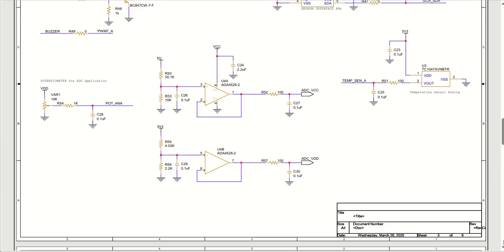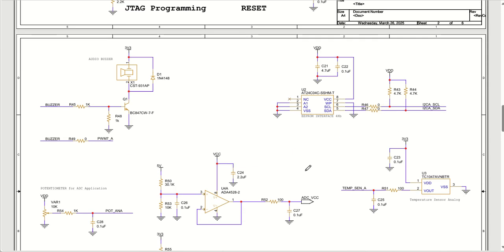Going to the next part of the circuit, this is the discrete part I was talking about: an audio buzzer just for alarm purposes, like a ting ting ting sound it can give you, so that you can understand we have something to attend to, right? This will be taking a 2.73 kilohertz PWM. This PWM will be of 50% duty cycle. All right.